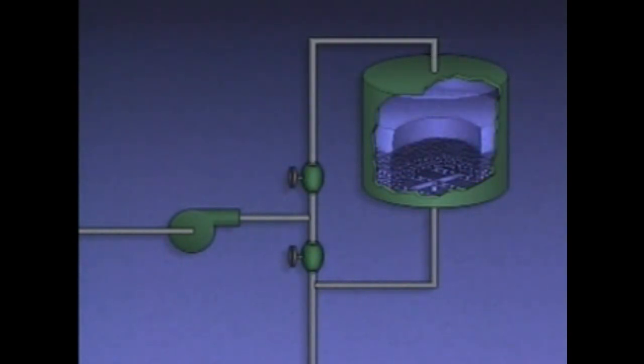As the water passes through the activated carbon, the chlorine molecules are attracted and become attached to the surfaces of the carbon's granules. Aerators are used in secondary water treatment to remove dissolved gases such as hydrogen sulfide and carbon dioxide. The dissolved gases are replaced with air.